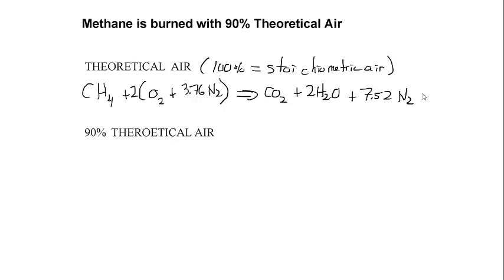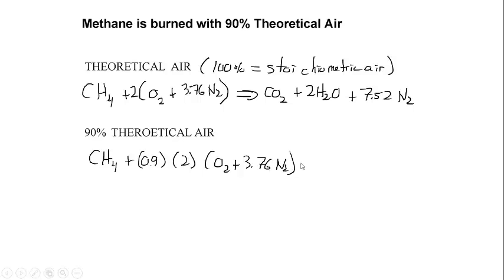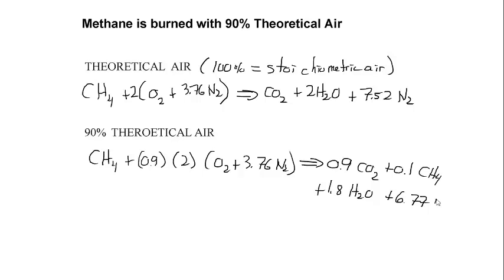If this were to be 90% theoretical air, I have my CH4 reacting with 90% of this: 2 moles of oxygen plus 2 times 3.76 moles of nitrogen. This would yield 90% of what was present before, with 0.1 moles of methane remaining. I hope that's clear.